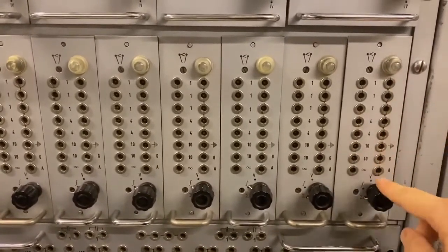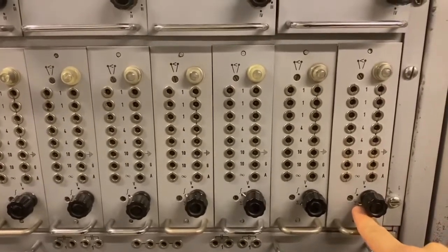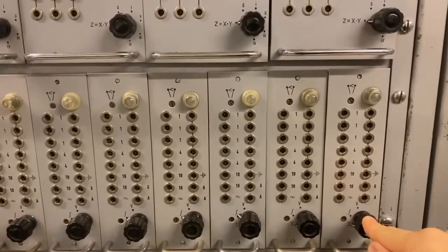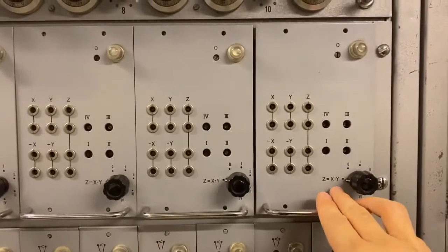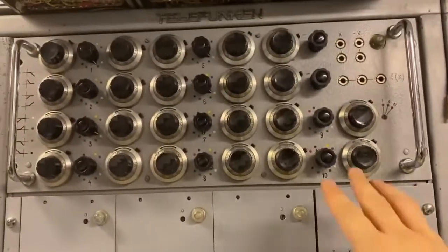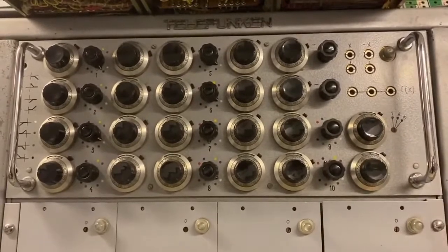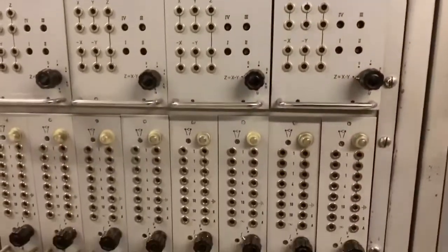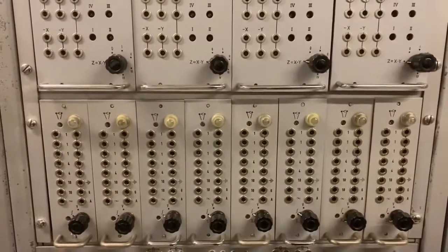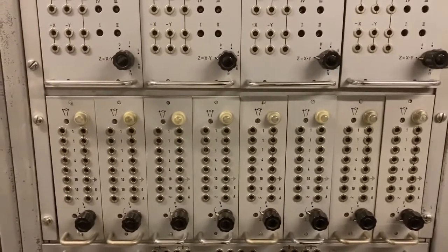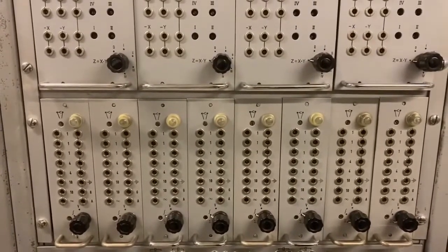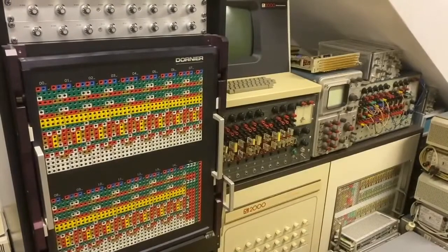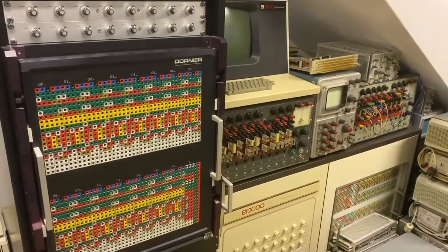For example, these elements can be switched to compute the sum of some values or the time integral, or can be used as open amplifiers for inverse functions or the like. You also have, for example, multipliers. This module performs multiplication. You have function generators if you need some arbitrary functions which you cannot generate mathematically in an easy way. And the idea of an analog computer program is now to set up an interconnection scheme between these modules so that the modules perform the mathematical equation which describes the problem you want to solve with an analog computer.